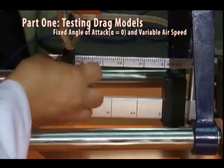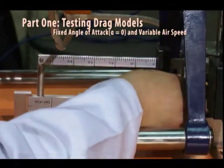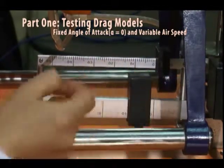If moving the small mass will not return the balance to the null position, the lower mass should be moved one increment of 0.5 newtons. This can happen at high airflow speeds.